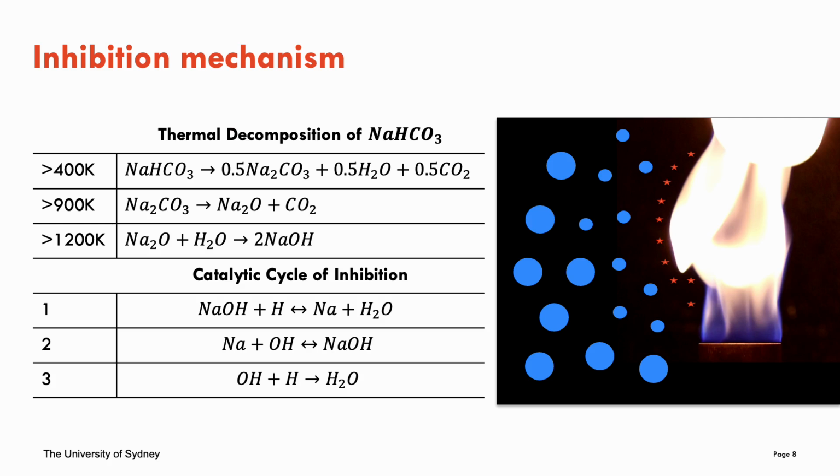So water mist we know targets the gas phase. So what this means is droplets evaporate near or in the flame front. And if you include inhibitors such as sodium bicarbonate in this case, what happens is, if you look at the diagram on the right, these droplets, as they come out of the co-flow, as they get closer to the flame front, the droplets get smaller due to evaporation, and once they fully evaporate, they release sodium bicarbonate crystals, and these crystals, at given temperatures, thermally decompose into your inhibitor, which is sodium hydroxide.